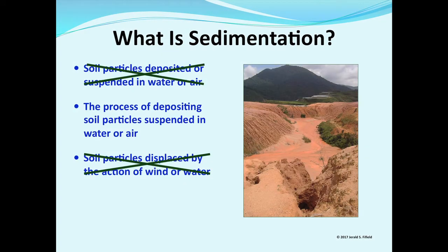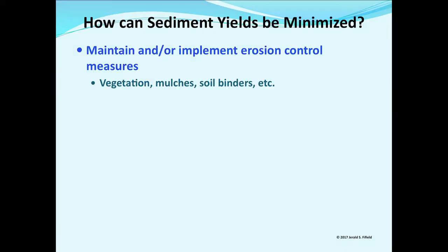How do you do it? And you say, well, we just put a barrier in front of an inlet. If anybody was in my class, I trashed inlets with a barrier in front pretty bad. They only work when it doesn't rain. If it rains, you've got a problem with inlet protections. So how do we minimize sediment?